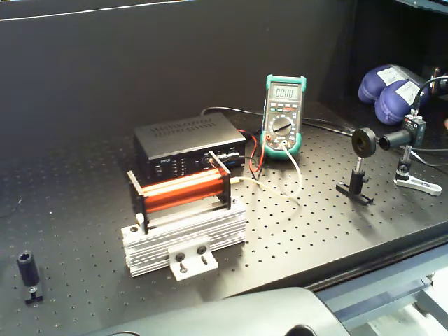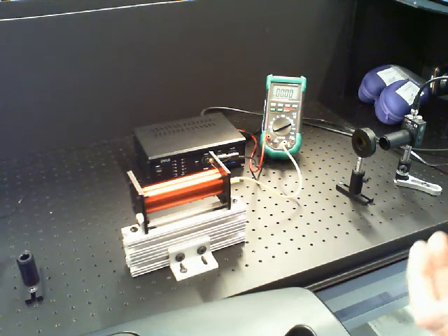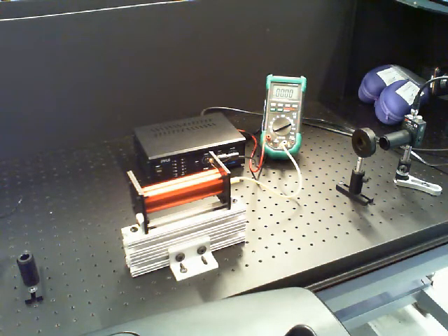It basically allows you to pick out a signal on your detector at the correct frequency and correct phase for what you would expect. Meaning you can be looking on an oscilloscope and seeing a very, very noisy signal, but you can actually extract the component of that noisy signal, which is your good signal, and reject all other signals except for your good signal. And it's a very powerful tool for seeing very small signals in a very large noise background.